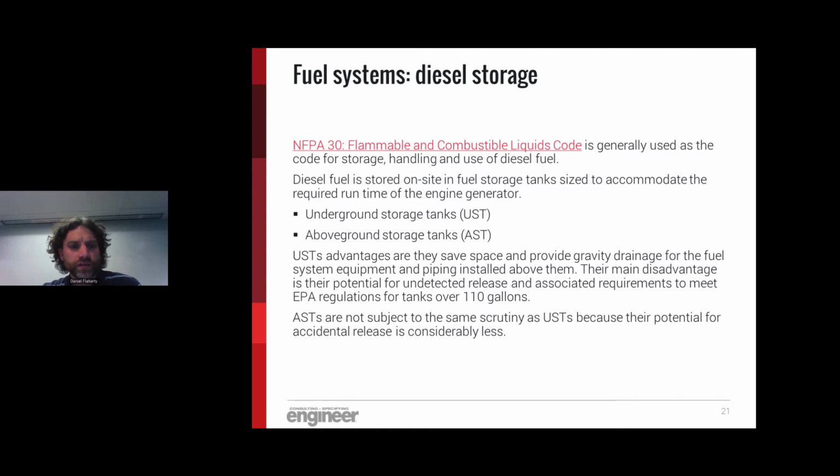Now getting into the diesel fuel systems, NFPA 30 is used as the code for storage, handling, and the use of diesel fuel. That code is going to tell you everything you need about piping, the tanks, and accommodating storing and handling the fuel to your engine generator. It goes over normal vents, emergency vents, fill alarms on tanks when they're at 90% so the operator doesn't overfill it, and mechanical fill valves that will actually stop tanks from being filled at 95%.